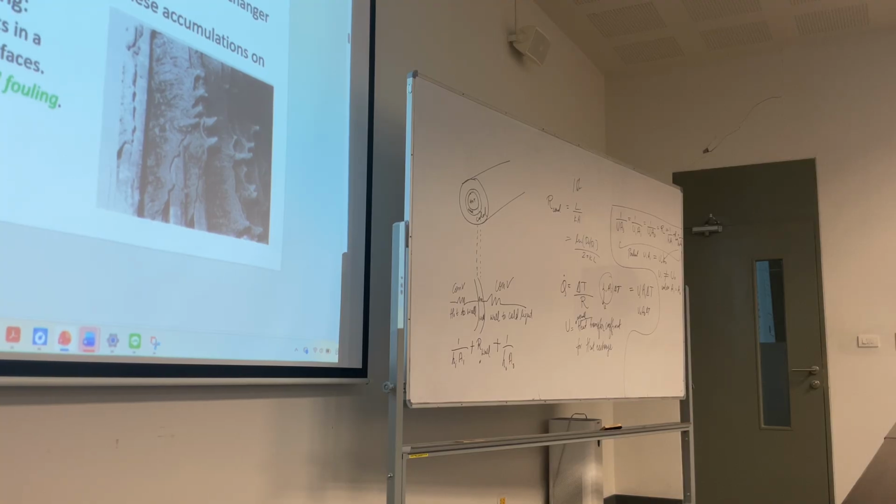These are only pipes. So if you are using the heat exchanger for a long time, you can have some salt deposit, or some other stuff. So the layer of deposit, this kind of deposit inside the pipes, inside the tubes, the layer of deposit represents additional resistance, right? So they represent additional resistance.